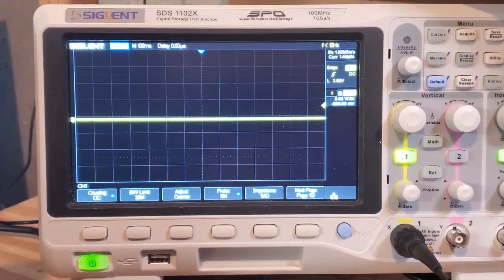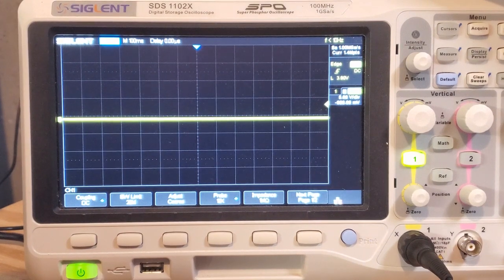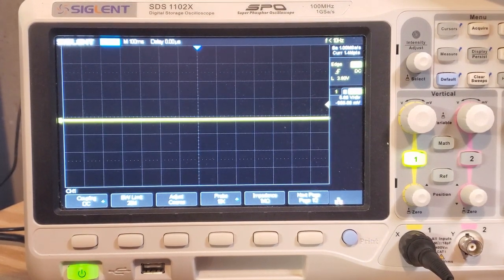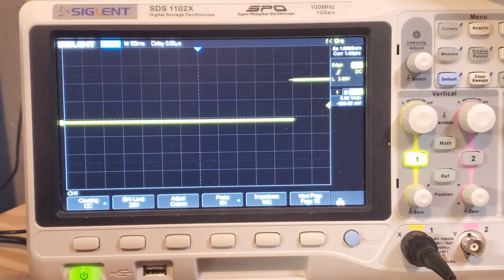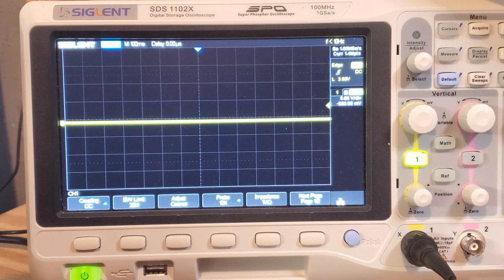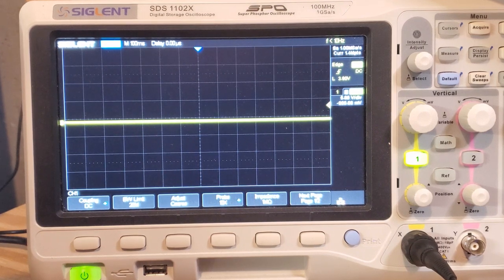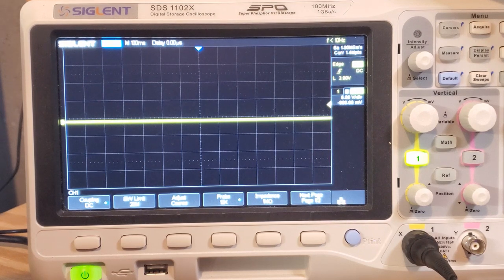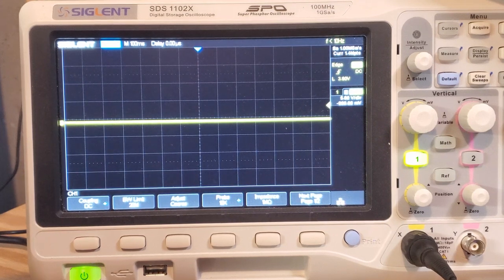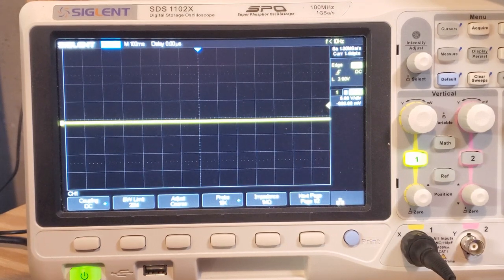Let's move up to the oscilloscope, and we should see that trace where it sustains the output with a momentary input. I'll click on the button, and you can see that sustained output. I'm just doing a momentary click, but that 2.2 microfarad capacitor is interacting with the LM3900 to produce a sustained output. Now let me swap that capacitor with a 470 nanofarad capacitor, and we should see a pulse of lesser duration.